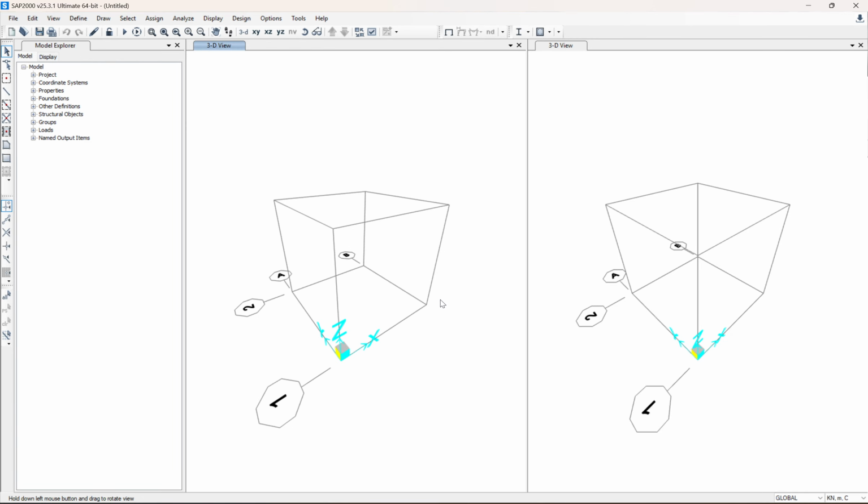So what you need to do is first draw a poly area. Imagine that our XY plane is the horizontal plane and the vertical plane is the XZ plane. So I'm drawing a poly area, this rectangle, and once you select that point, you can press enter.